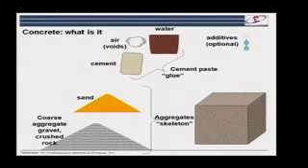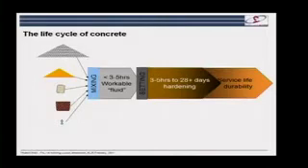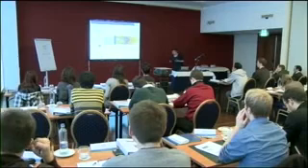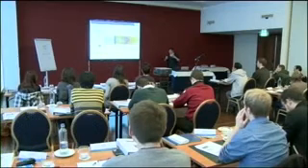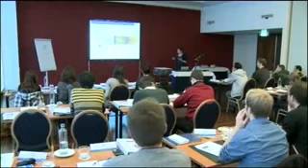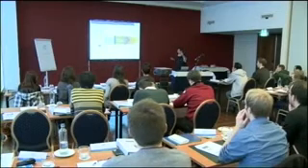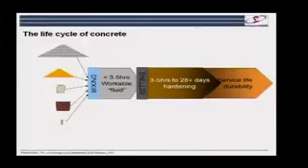We're not going to talk much about this today, but additives are becoming an increasingly important part of modern day concrete. If we look at the life cycle of concrete, we take those raw ingredients, we mix them together, and then for about 3 hours or so, we have a workable fluid, and then we have this transformation from something that moves, where everything can move in space, to something that sets, becomes rigid. This is not a single point in time, but a continuous process, and that hardening process goes on over roughly the first 28 days or so.